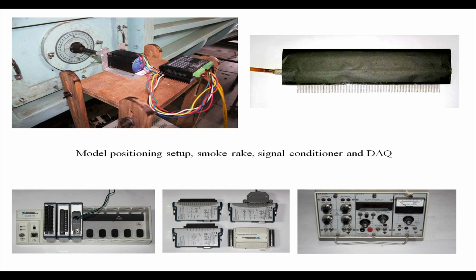It is not a dynamic change of angle of attack, because we are not looking at the dynamic characteristics of the airfoil. So, I hope you understand the implication here, that the airfoil is a lifting surface. So, there is going to be a difference in pressure distribution between the upper and lower surface of the airfoil. Of course, it depends on the kind of airfoil section you are talking about. If you have a symmetric airfoil section, then at 0 angle of attack, you know that there is no pressure difference between the 2 surfaces, and therefore, it does not generate any lift force.